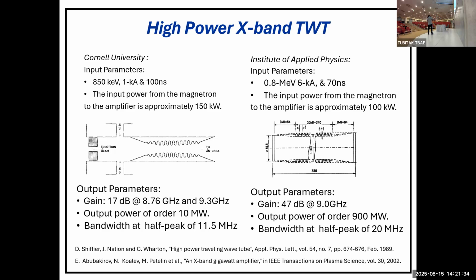So some people, if they don't know about this field, start having the reflection maybe here, or maybe they have a slow wave structure that continues through this whole region. That's going to be bad for your amplifier, because if you introduce reflection at the edge, that means you are enhancing the feedback. So you don't want to do that.